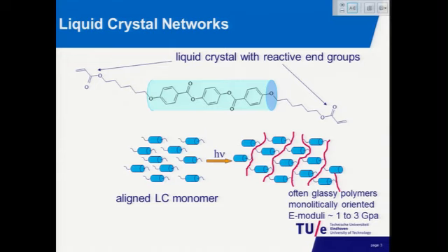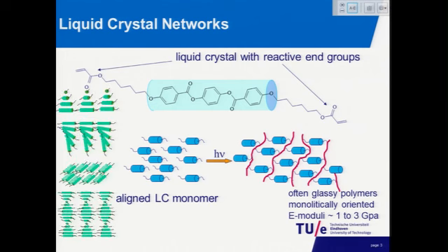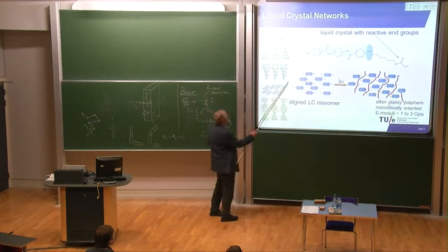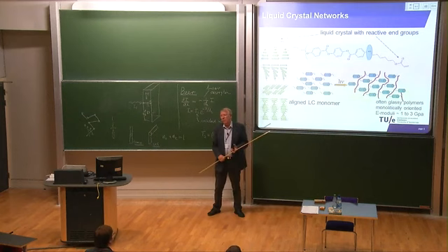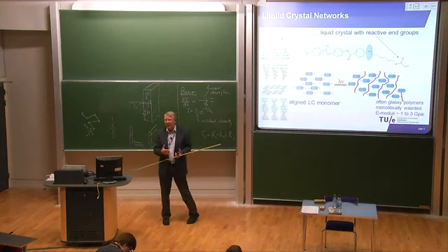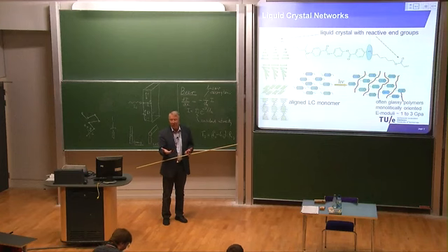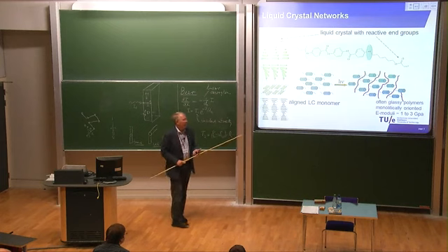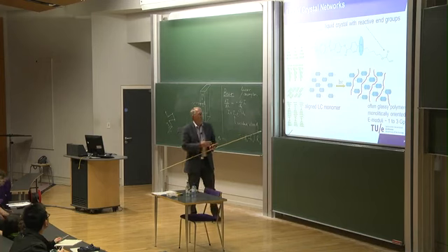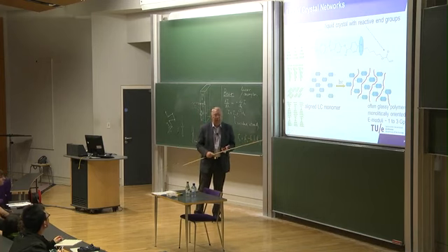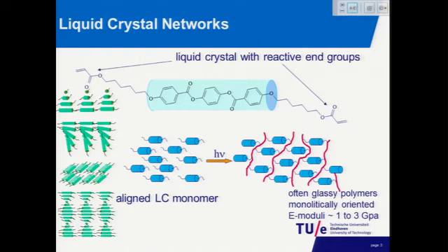Well, as we are using the low molecular liquid crystalline state to manipulate the molecules at the beginning, we can play many different tricks, so to say. We can decide to align them uniaxially, as is shown here, just by applying the monomer on a surface with some pre-alignment. For instance, you take a plastic coating, a polyimide coating, you rub it with a velvet-like tissue, and then this brings microgrooves into the polymer, which are taken over in its orientation by the liquid crystal.